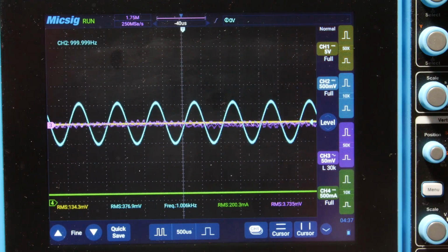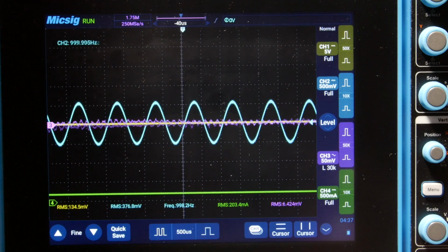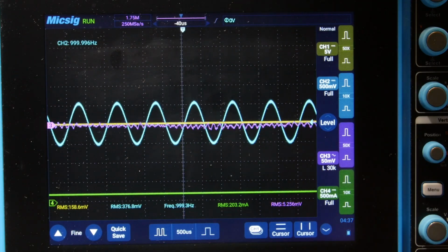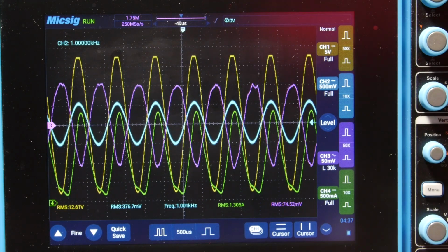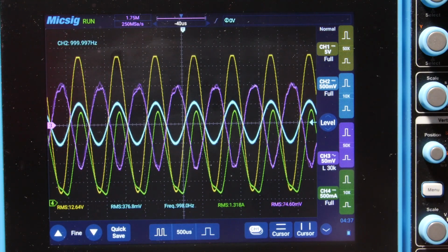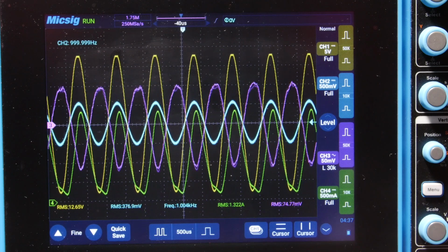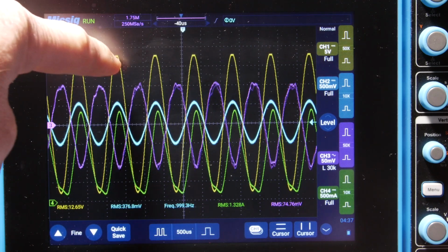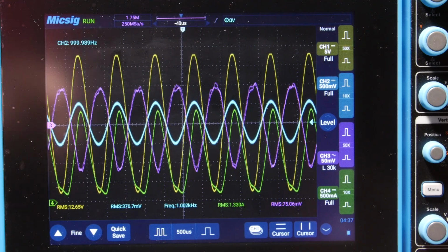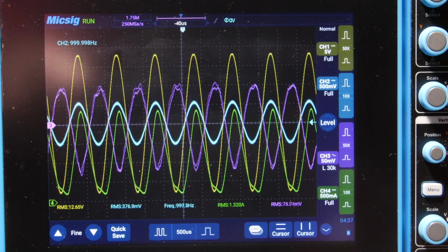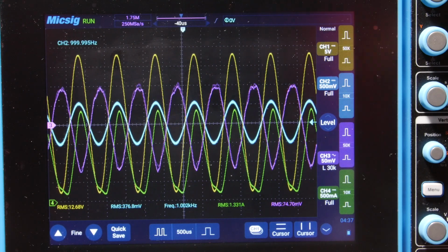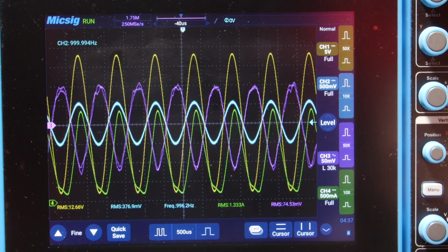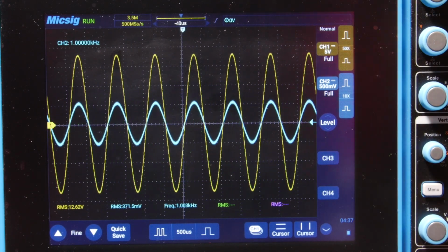All right, so you'll hear the power supply go on. All right, and I'll bring up the rails. And it takes just a moment for the power supply to fully come up. You can kind of see it was flatlined or is clipping a little bit. Okay, so the yellow one is the output signal, the blue one's the input signal. Turn off the other two just for a moment so you can look at them. Okay, there's input and output.